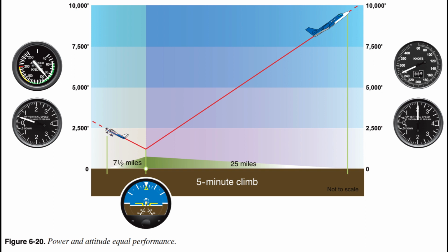As the performance capabilities of the aircraft are learned, a pilot interprets the instrument indications appropriately in terms of the attitude of the aircraft. If the pitch attitude is to be determined, the airspeed indicator, altimeter, VSI, and attitude indicator provide the necessary information. If the bank attitude is to be determined, the heading indicator, turn coordinator, and attitude indicator must be interpreted. For each maneuver, learn what performance to expect and the combination of instruments to be interpreted in order to control aircraft attitude during the maneuver.